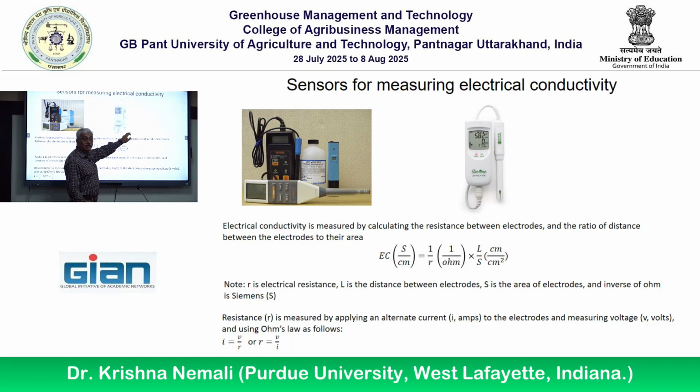The probe is right down there. In that probe, you'll have electrodes. Okay. The bulb is probably one of the electrodes, and inside there is a small sort of metal wire or something that will be another electrode. That's how they create these electrodes right in that bulb. So if that bulb breaks, the meter is gone. So you got to be very, very careful.